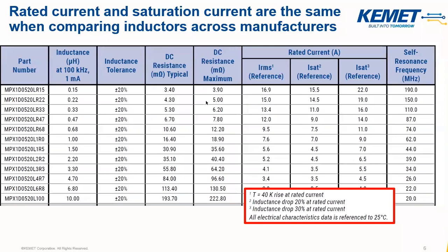So what you end up doing is, under the use condition, you find out that you can put a much lower current through vendor B than you can through vendor A, even though on paper vendor B looks like a better component. So it is a bit, the devil's in the detail. You have to go and look at the specific use condition of the component and compare the two vendors. Yeah, the conditions under which these rated or spec'd out numbers have been determined. Correct. Okay.